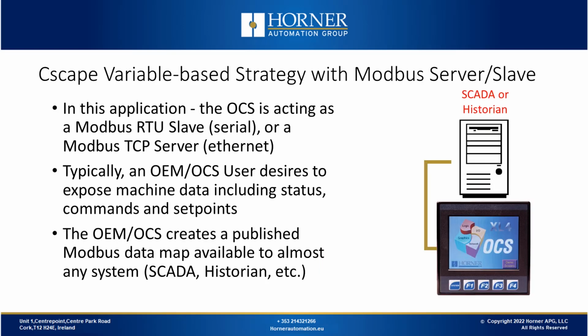Next, let's talk about a method using variable-based advanced ladder in Cscape for applying an OCS controller as a Modbus slave or a Modbus server. As an OEM or machine builder, I want to supply my equipment so that the important data that resides in my machine can be accessed by my user, such as status, commands, and setpoints. In this application, we want to create a published Modbus data map to make key data available to almost any system they are using, whether that be a SCADA package or a historian, for example. Modbus is great for this as it's the most common protocol, and so it can interface to many different manufacturers' products.